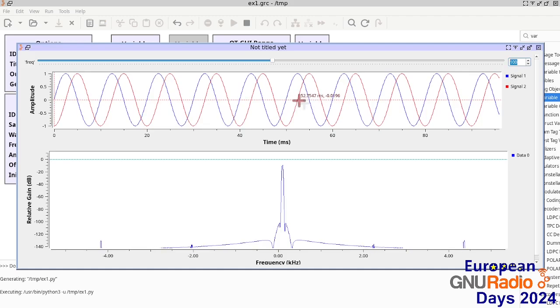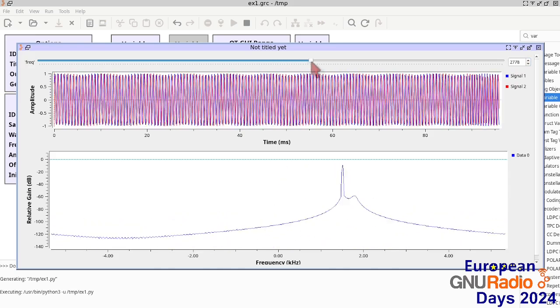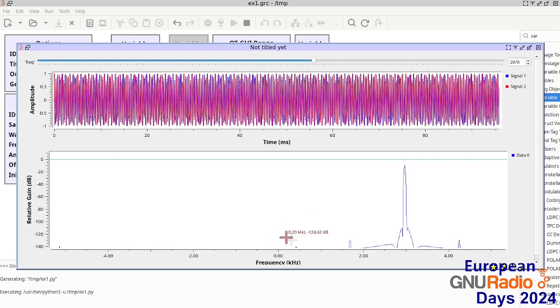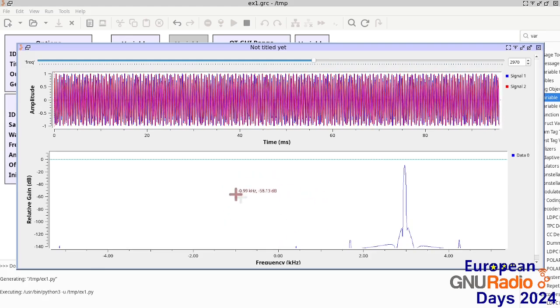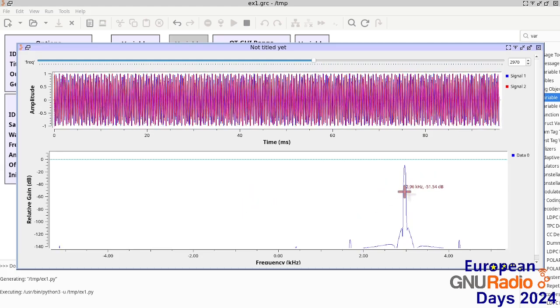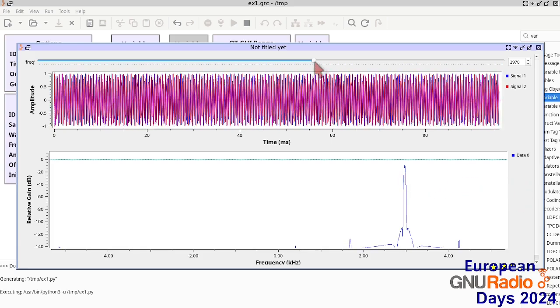So this allows you to see a little bit what is the meaning of this awkward quantity, and furthermore you can have a new insight into what aliasing means if we bring in this complex number. Remember when we had a real output cosine, we had two peaks, one at minus omega and one at plus omega, and we had the feeling that when we reach the Nyquist frequency, the peak here would bounce back into the baseband.